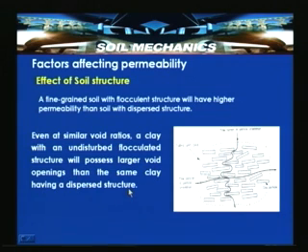We have also discussed that a flocculent structure can have more flow because of the truss like arrangement, having a 3-dimensional or random arrangement with large openings or large pore spaces. So, the larger the pore spaces, the more is the flow. That is what we have discussed. K is proportional to D, which is the size of the pore spaces.